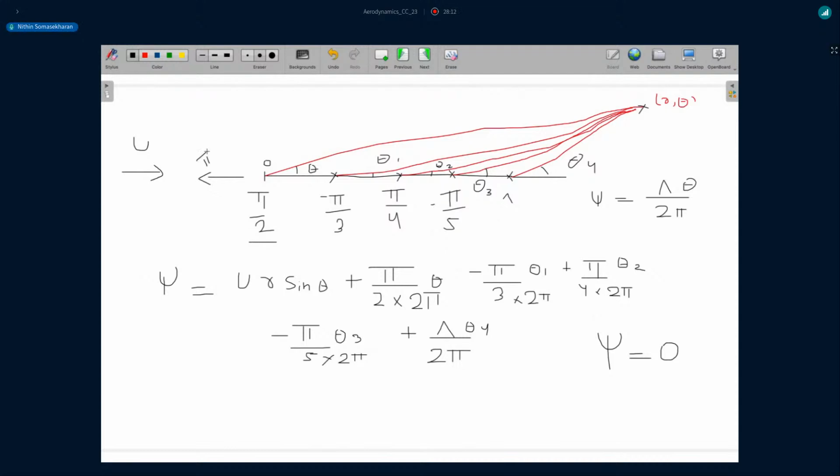So if I go in my 180-degree direction, there is a stagnation point over here, and at some distance r from the center, I'm going to meet that particular point. And we know that the stagnation point will basically pass to the stagnation streamline, making psi equals 0. All right.